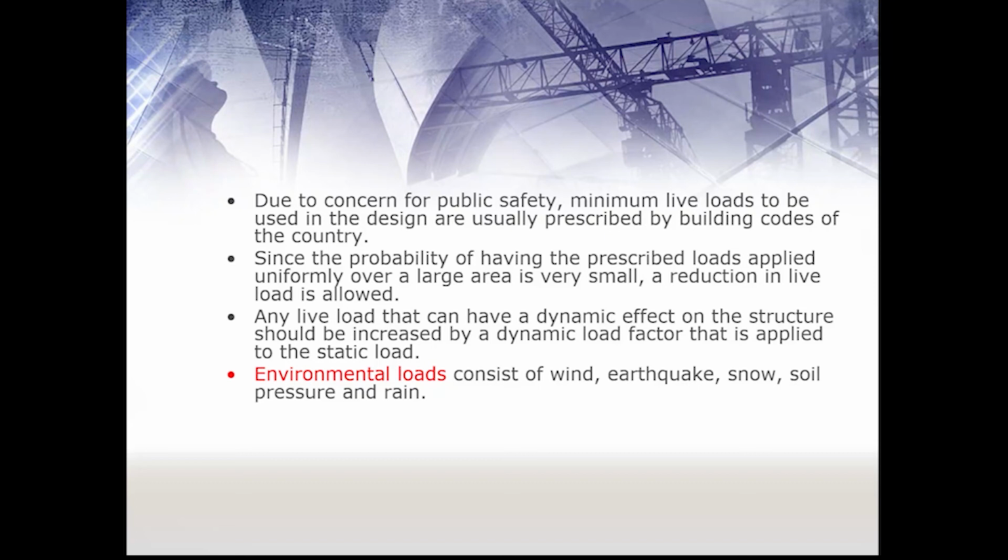And the earthquake also is considered depending on the area. If your area doesn't have any earthquake, you don't need to consider earthquake during the design. The same way for the snow, some regions or some countries don't have a winter season where it snows, so they don't need to consider snow during the design. But the soil pressure and the rain may also be very important to consider among the types of environmental load we use.